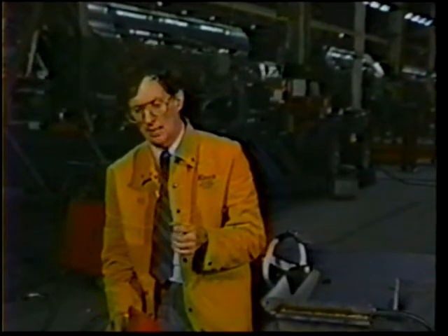What we've discussed in this training film is really understanding parameters. We don't have to remember the amperage for every thickness. We simply have to remember that if we're welding thin metals, we put the wire feed around the 11 o'clock position, or if you have a digital wire feeder, set it around 150 to 200 inches a minute. And remember to put the voltage for short arc at 17, 18 volts. If you're welding very thin metals, then put the voltage at 16 volts.